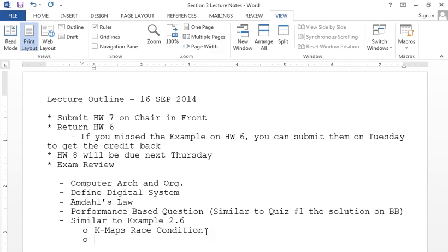So let's say it's going to be B not A or C, and then B, A, and C. Let's say those are our functions that we derive. So what's the literal cost for A or C? 2. Why is it not 1? C, exactly right. I've never made mistakes on the exam. And so what's my inverter cost? 0. So what's the total cost for the B map?